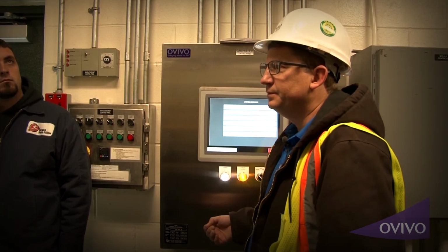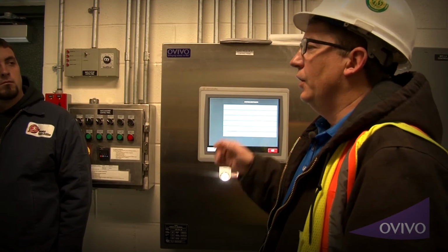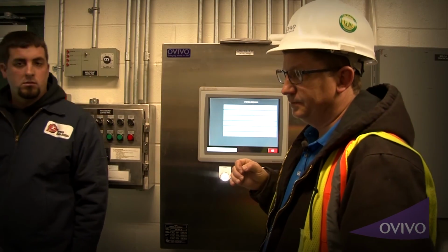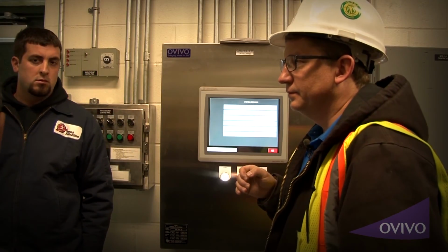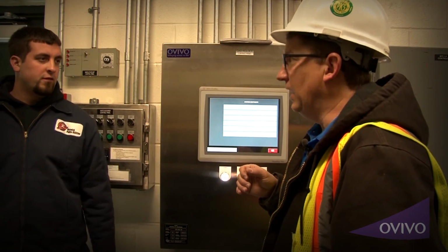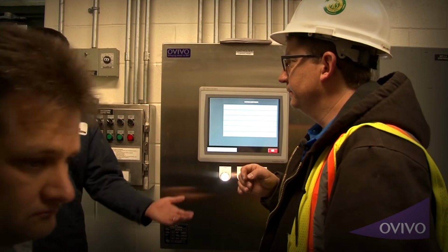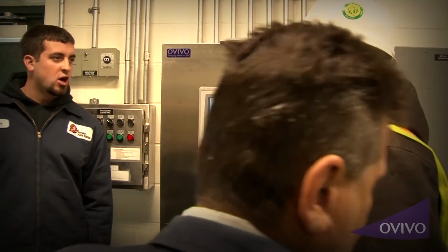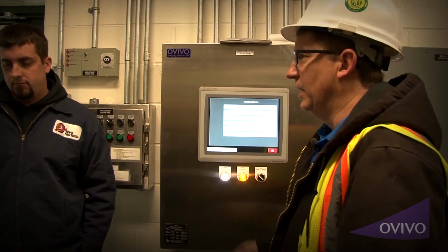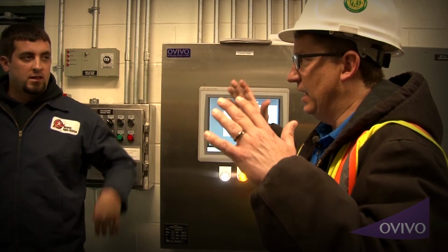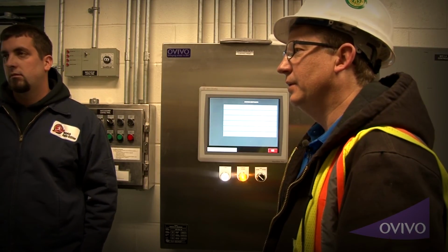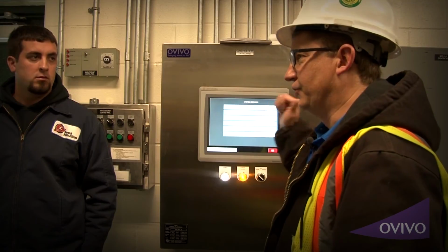Did you actually lose pressure that way? You're going to lose it pretty quick at the higher pressure. It's exhausting, but those outside TRVs should shut. They're pretty much always open at that initial start. If you kept this off for an hour, it's probably not going to drop much beyond that. Over the course of an hour, you could probably get it down to 5 inches of water column, maybe. As it lets out more pressure, there's less weight to pull on it. But shutting off the blowers for a couple seconds was enough to lose enough pressure to trigger the alarm.